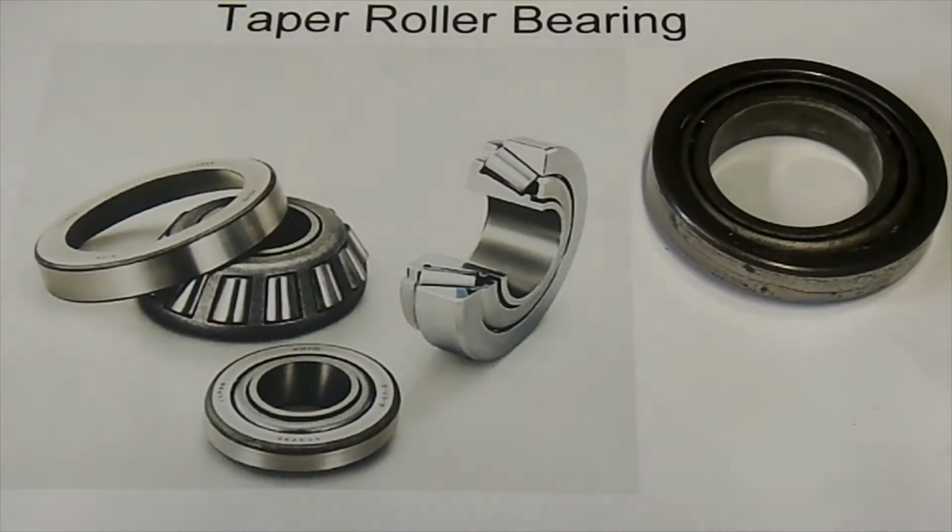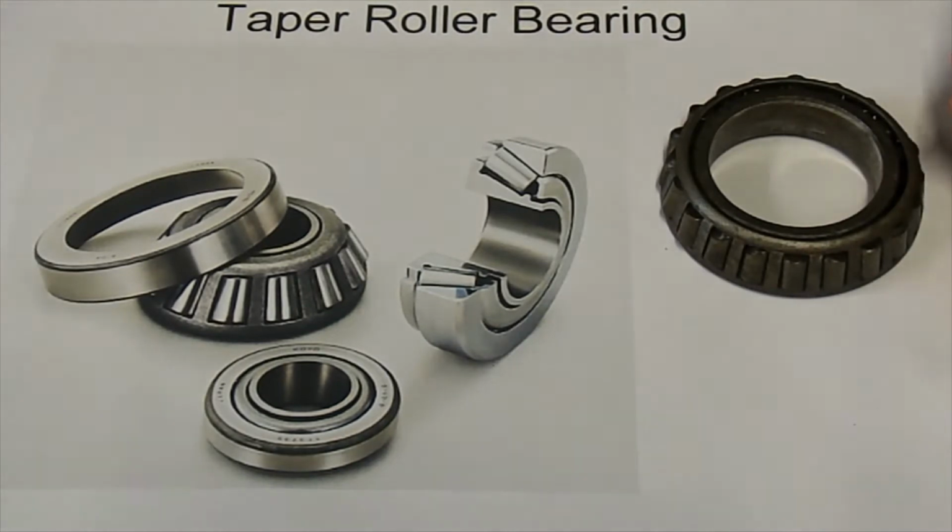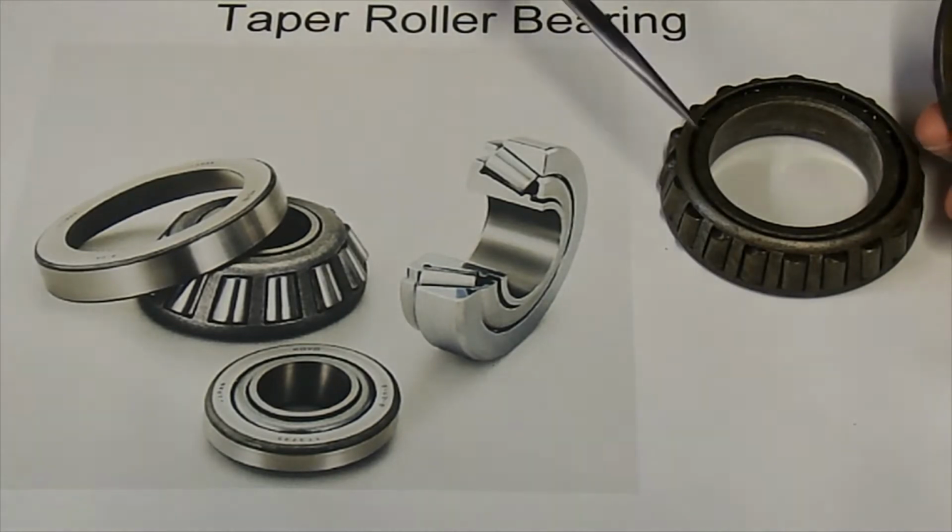Taper roller bearings are a common engineering selection because they're the only bearing to satisfactorily deal with both high radial and high axial loads. The bearing surface area is larger than ball bearings and so can take higher loads. The bearing splits into two parts and must be carefully installed and adjusted to maintain the correct internal clearances.